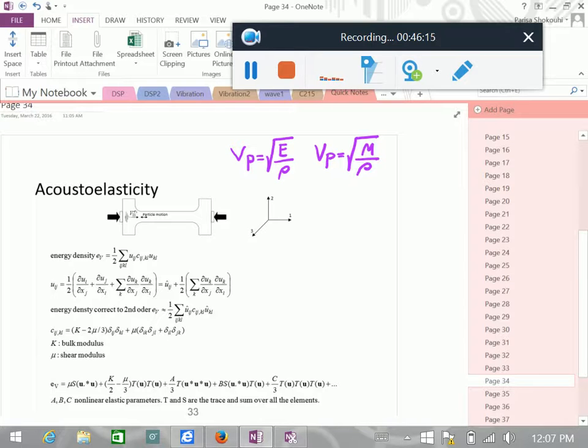I have to tell you also that in steel, after we did these experiments, I learned about acousto-elasticity a lot more. And in the 1950s, in steel, people already knew that there is acousto-elasticity. So it's, I would say, a standard measurement in steel to go and measure the velocity and relate it to a stress. People know this in metallic materials. But in rocks, it was the 1990s, and this was a decade later in concrete.